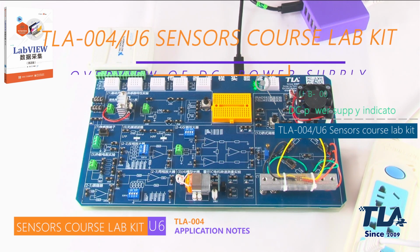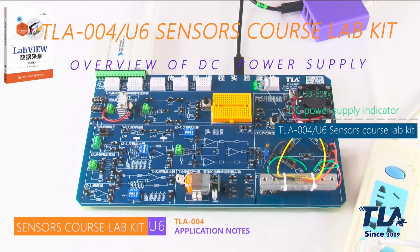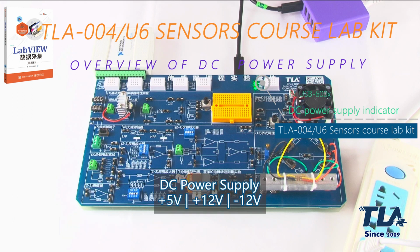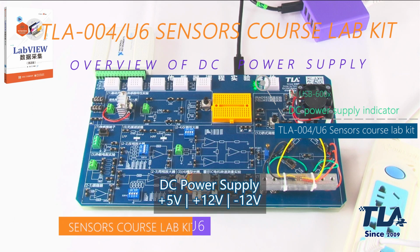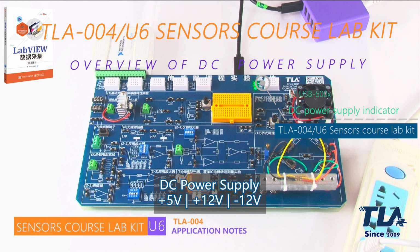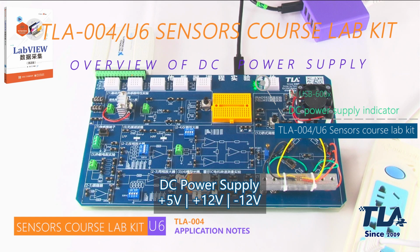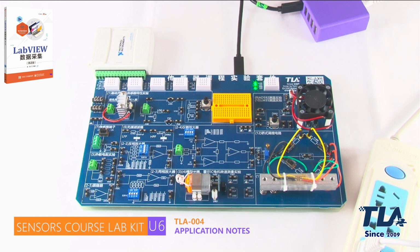At this time, it can be seen that the 3 power indicators in the middle and upper part of the kit board will light up immediately. The voltages of these 3 DC-regulated power supplies are plus 5V, plus 12V, and -12V respectively. Their terminal is located in the breadboard on the right side of the power indicator.